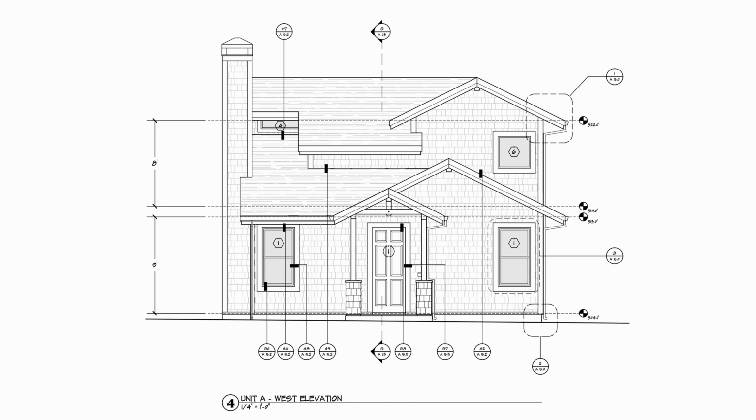And so all of these little circles and marks are specific details about how I want this built, how I want that built, how I want you to deal with this, how I want the eave built, etc. We get numbers on the windows, so it goes in a door and window schedule, numbers on the doors. So you know exactly what type of door it is, exactly what type of window it is, so that you can hand this to a general contractor and have them actually build it. So it's 3 elevations, and they're for 3 distinct different purposes. And the line weights and the drawings reflect those 3 different purposes.